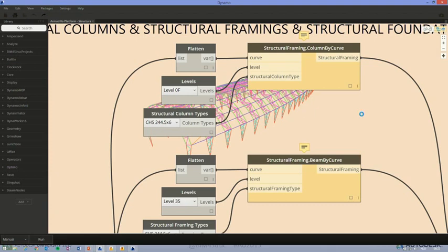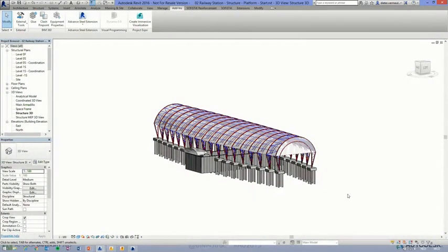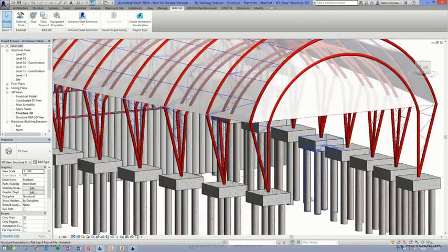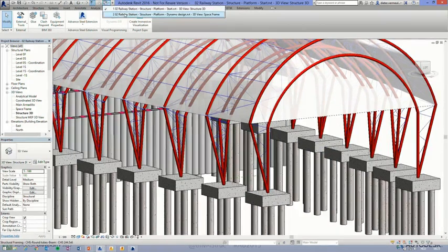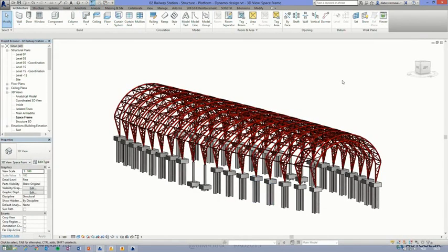So it's each time the same principle, taking lines, making points on it, and reusing those points. This means now, if something changes in here, if I, for instance, change the truss height to 2 meters, and run the script again, let's zoom out a little bit. You've seen it? Every element is repositioned because of that parameter. Now, if I connect this design with Revit, then I will have the same action, the same reaction of Revit on that. So making new trusses, or not making new ones, it will reuse the same ones and regenerate it.